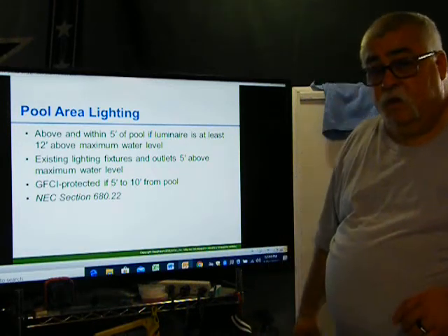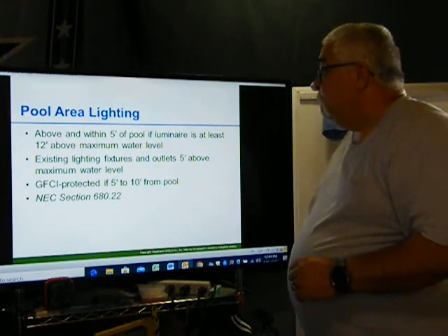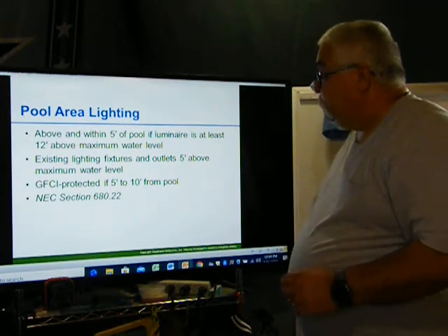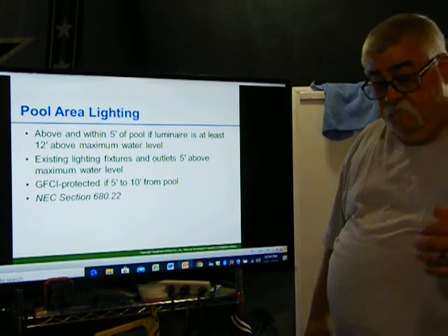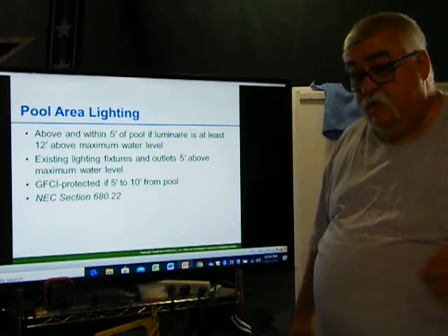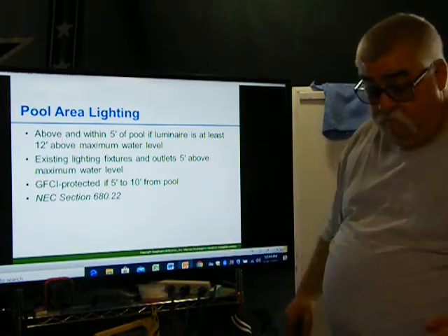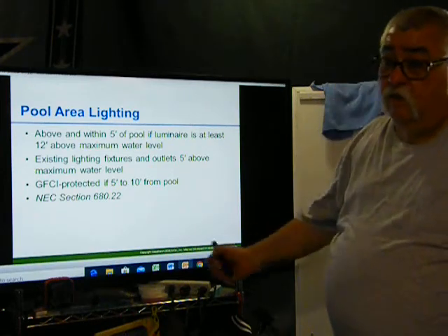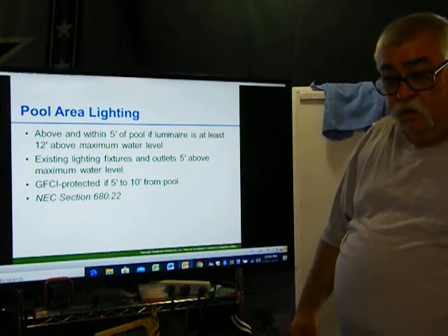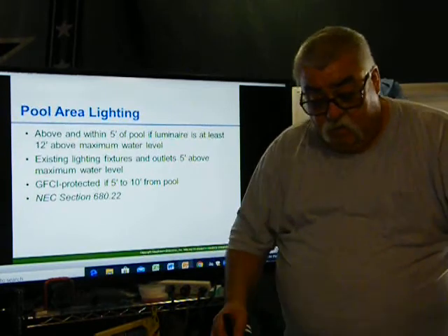Unless it's just cord and plug connected, and then it's completely different. Okay, we'll get into that in a bit. But if they're fixed light fixtures, once you get outside 5 foot, height does not matter. If you're putting them outside, obviously they have to be designed to be outdoors.